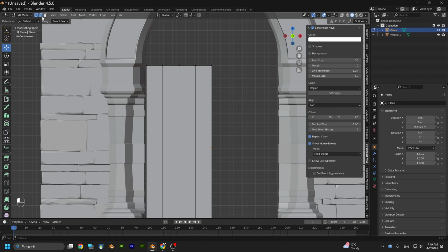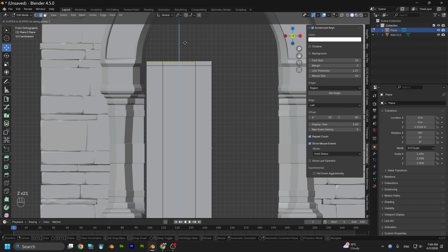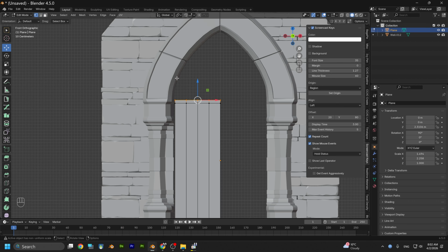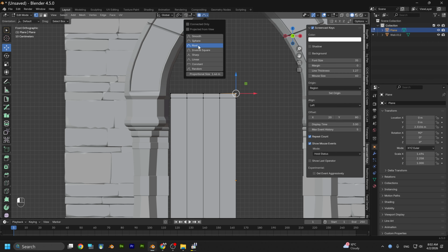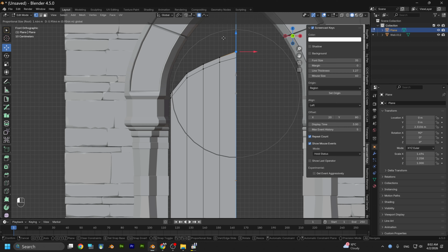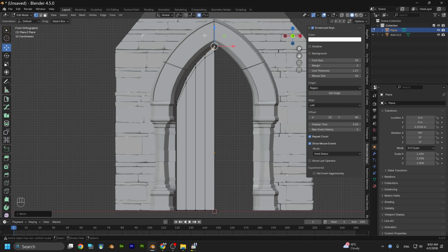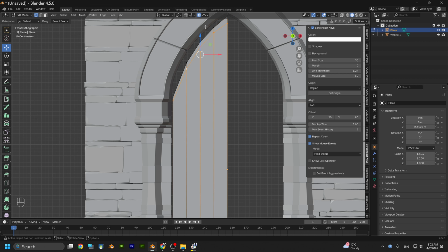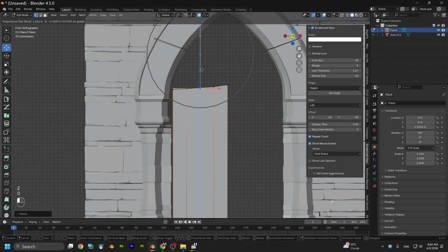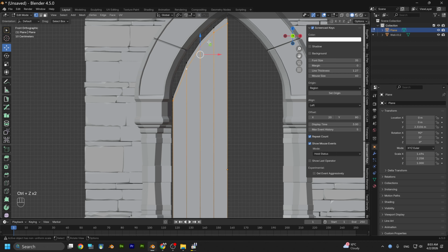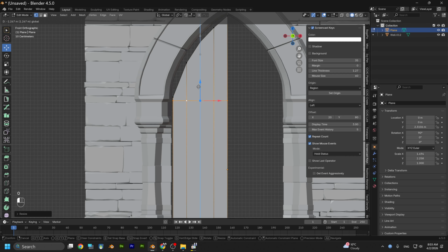And here we're going to select this. We're going to extrude on z-axis, and let's turn on vertices, and let's select this one here in the end, and here you need to choose root or something sharper, and we're going to pull this, and we will try to match as much as possible the shape of the arch. So I'm going to keep this like this, and these vertices, we need to be on SZ0. Sorry, I need to turn on the proportional editing, SZ0, and move them down back to the position.